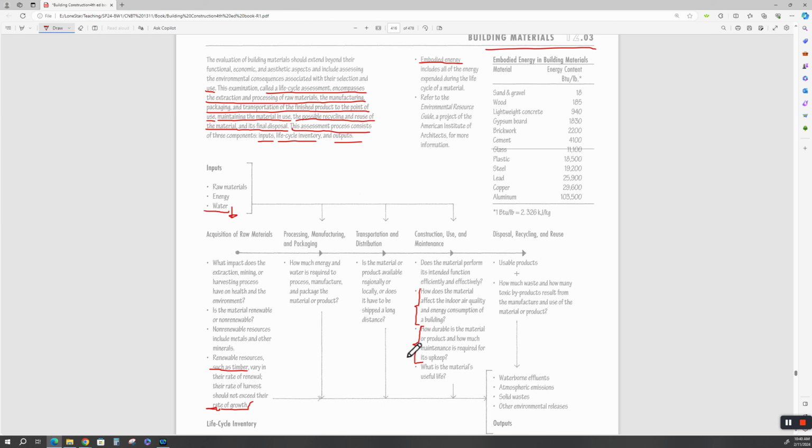Is there a better product? Maybe I should use Hardie siding. It's a fiber cement siding. I've mentioned Hardie before. I like Hardie siding, but it needs to be put over wall sheathing, over your studs, so that you're not asking that brittle concrete panel to span the stud distance. Give it a uniform base.